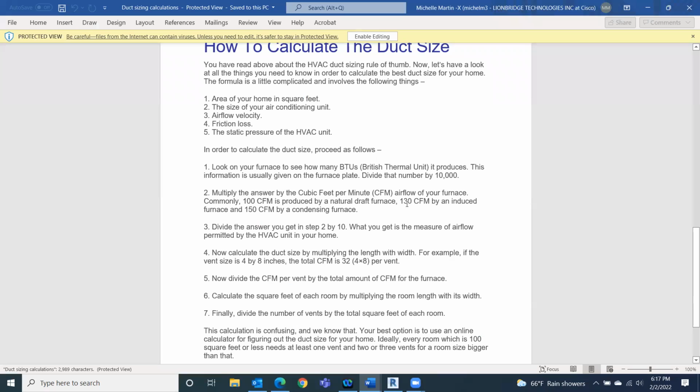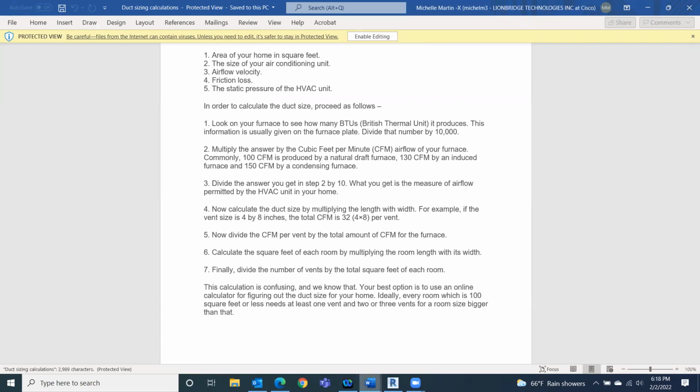So use that 300 figure here for your condensing furnace. That'll equate to that vent size that I showed you there. So use that here. And then finish this calculation as well. So this is what we'll need for Monday with your other information, with your completed BIM model.